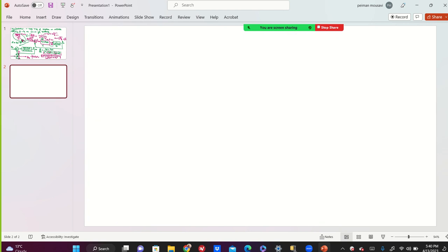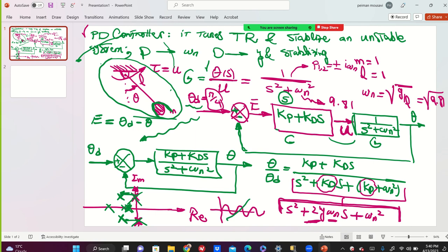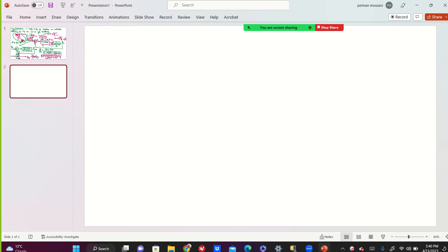I'm saying, okay, John, Elizabeth, go and design for me a controller that not only removes the oscillatory motion of the pendulum, but keeps it at 45 degrees, with an underdamped response. As I stated in the previous class, the maximum overshoot for the underdamped transient behavior is 25%, and the peak time is 0.2 seconds. I'm going to do this in MATLAB today together, okay?